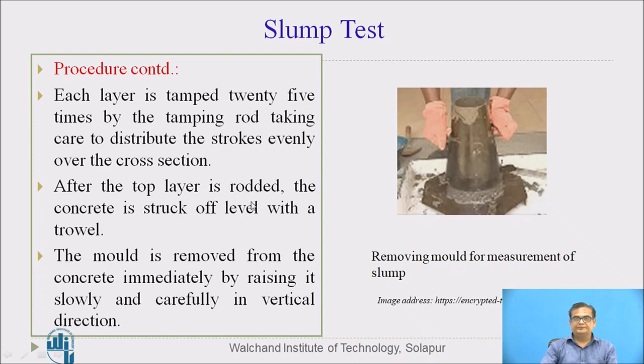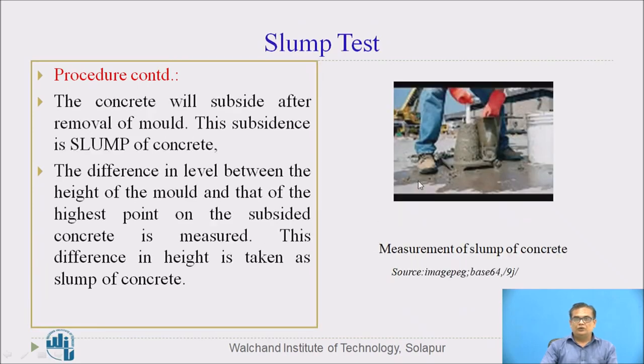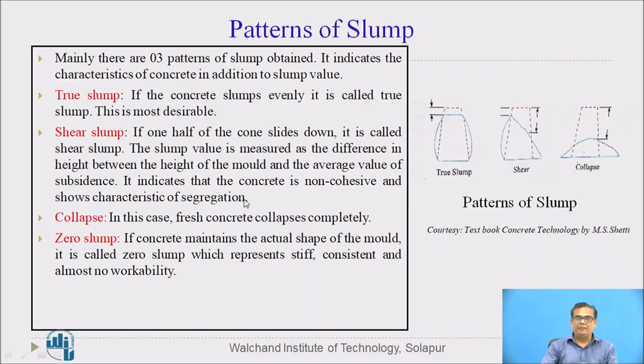Here you can see. Now the concrete will slump or subside. Now what is the level difference between the height of the mold and the subsided surface of the concrete? That is measured and it is reported as slump of that particular concrete in mm.